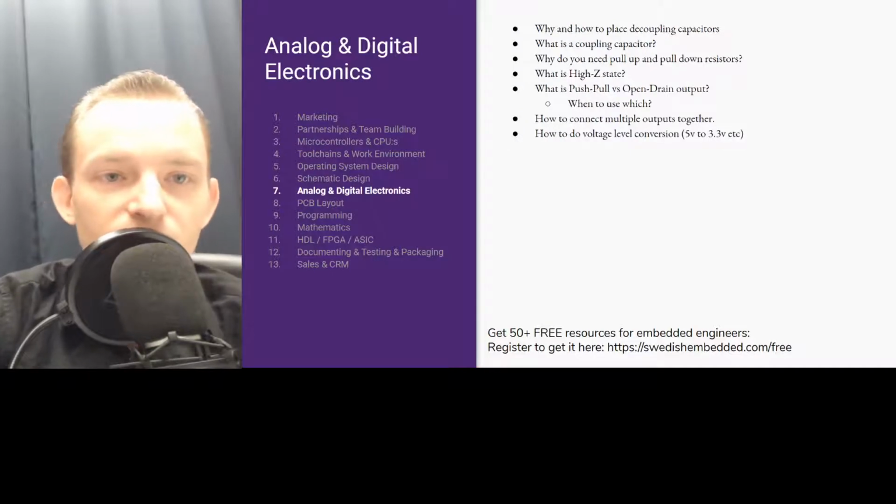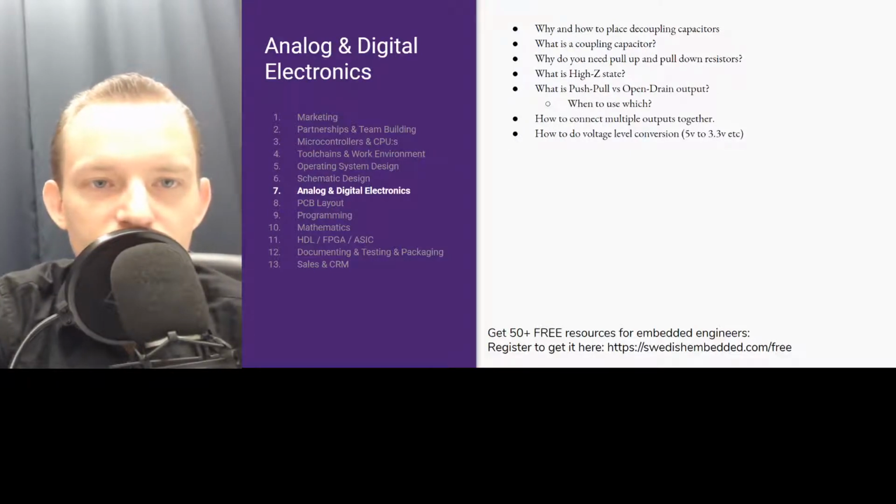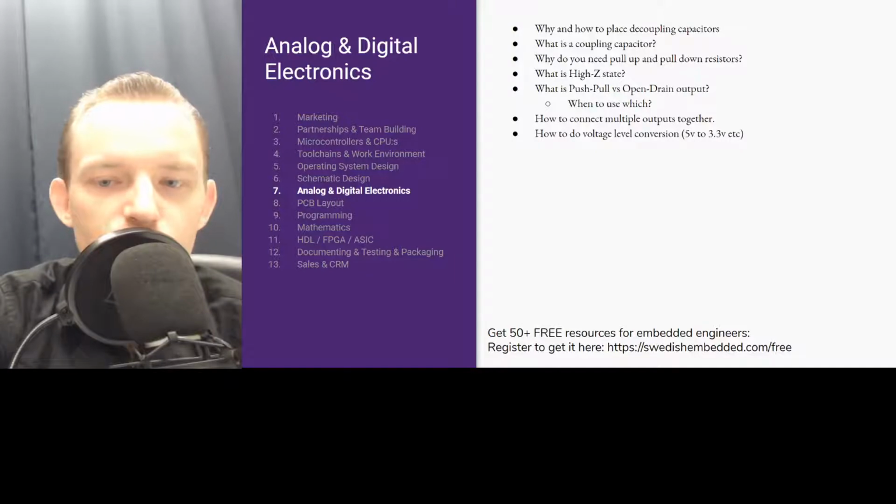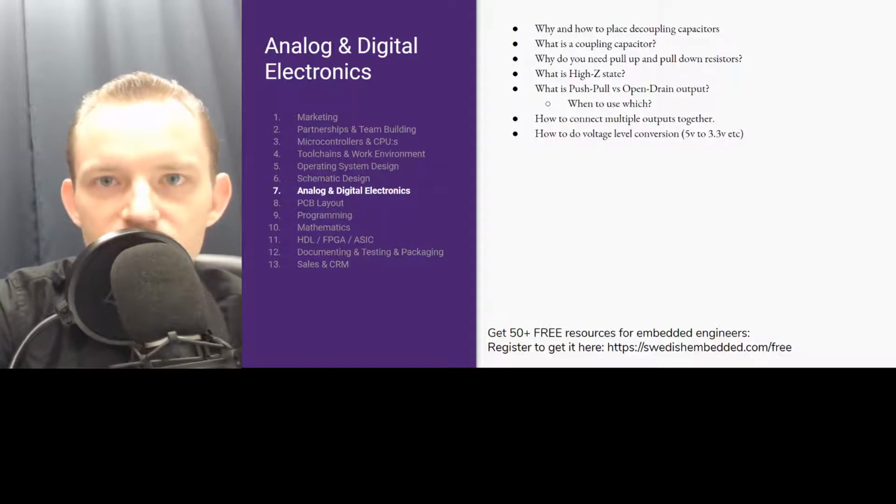And number 7, you need to learn analog and digital electronics. So why and how do you place decoupling capacitors? Why do you need them? When do you need to have a coupling capacitor? A decoupling capacitor would filter out noise, and a coupling capacitor would filter out DC currents. So it's going to let through higher frequencies, but filter out DC currents.